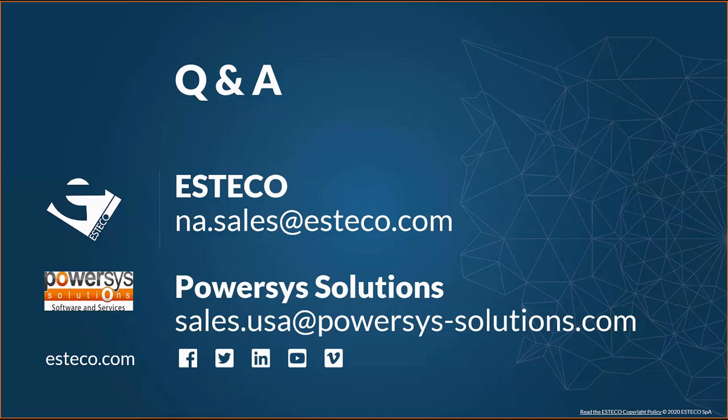Yeah, so this is Dheeraj, I'll answer that question. Basically, in this case, we went with what creates a valid geometry. There are some parameters where they coincide and might not create a valid geometry, but we included those still so as not to skip over them. But JMAG actually has a built-in rangefinder function that can run through these iterations. Once we give a maximum and minimum value, it will run through these iterations to give possible ranges for those parameters.